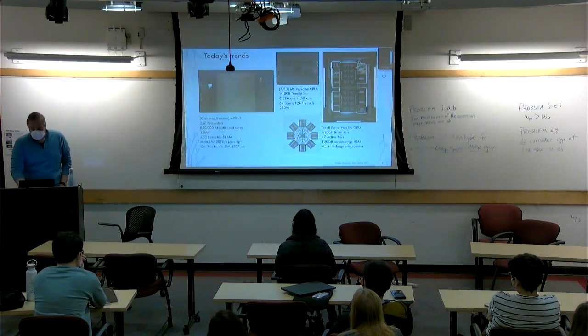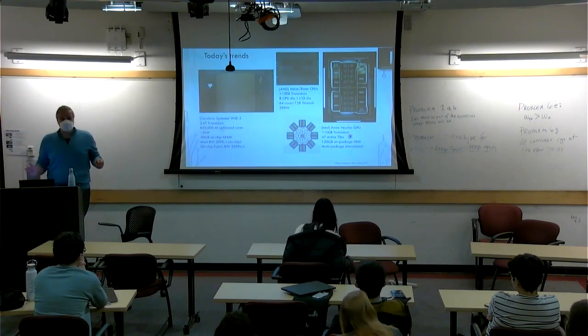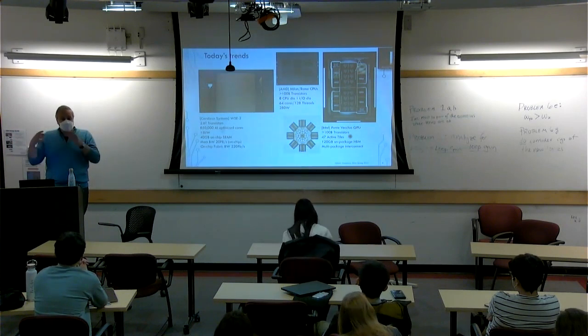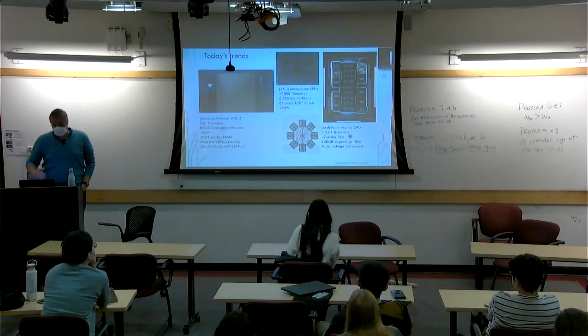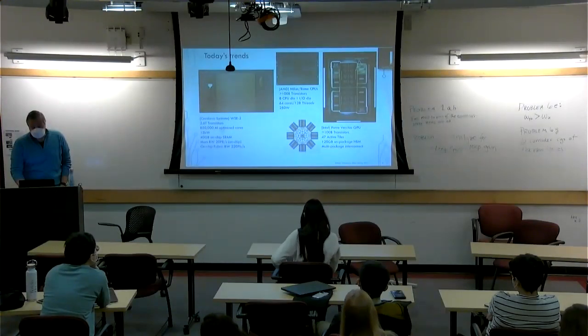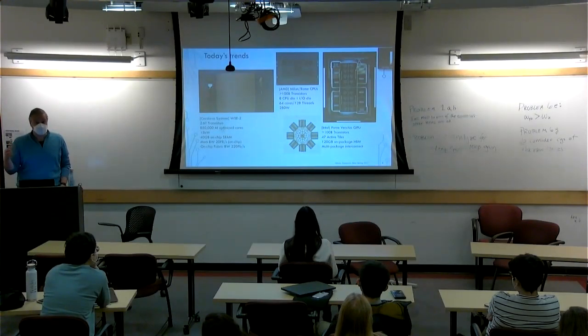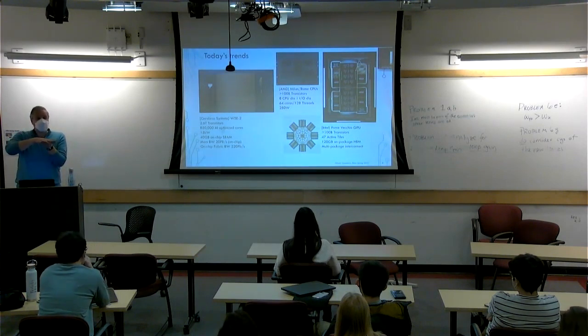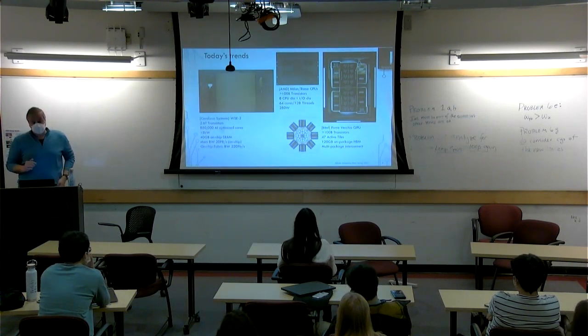And then you have monsters like Ponte Vecchio. This is the GPU that Intel's planning to roll out hopefully this year. If you look at it, it's about a 20th of this system, but it consists of 47 different chiplets. Some memory, some compute, some cache, some IO, etc. And actually different technologies. Some are in Intel, some in TSMC, etc. So it's kind of like a mix and match platform. And they also have 3D integration. Foveros is a way to basically stack wafers on top of one another and provide shorter routes, let's say, to memory, right? Or cache.